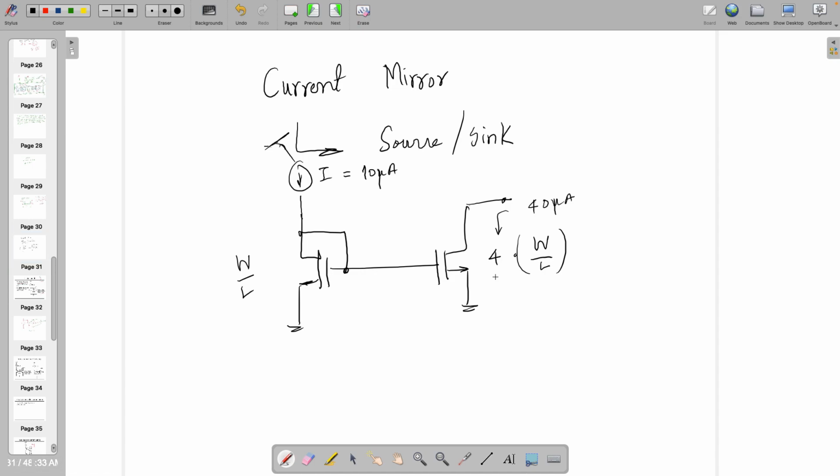But if you remember, there is a channel length modulation also. So if you want to get rid of it, you can do this one. Does not make much difference, but with 3L, around 3L should give you the stable RO. If you are increasing more than that, might not give you so much benefit, right? So this is what we learn.